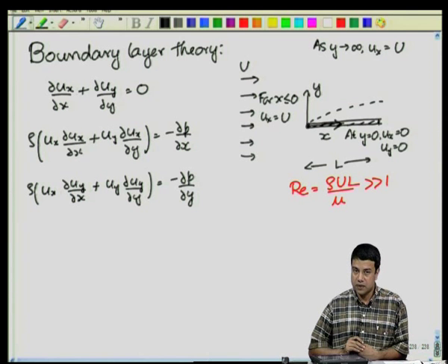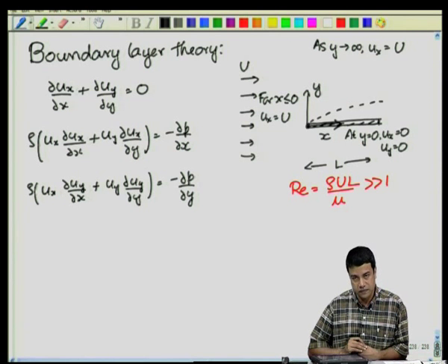If I put in u_x equal to capital U, u_y equal to 0, and pressure P a constant, half rho u squared, you can easily verify that it identically satisfies all of these equations. What it does not satisfy is the boundary condition at the surface of the plate, and therefore, somehow we have to bring in viscous diffusion perpendicular to the plate in order to be able to satisfy the boundary condition at the surface of the plate.